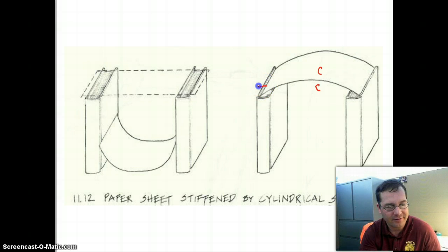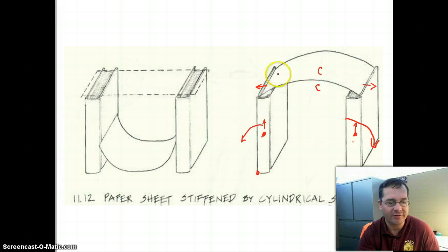They're developing this outward thrust, trying to push these books apart. But, of course, these books have some center of mass, which is not right at the edge of the book. It's in the center of the book, which means that if this book is going to roll this way, it's going to have to pivot about this point, and if this book is going to roll this way, it's going to have to pivot about this point. And in both of those cases, that's going to require lifting the center of the mass of the book. The result is that these books are able, at least to some extent, to resist that outward thrust and prop up this arch.